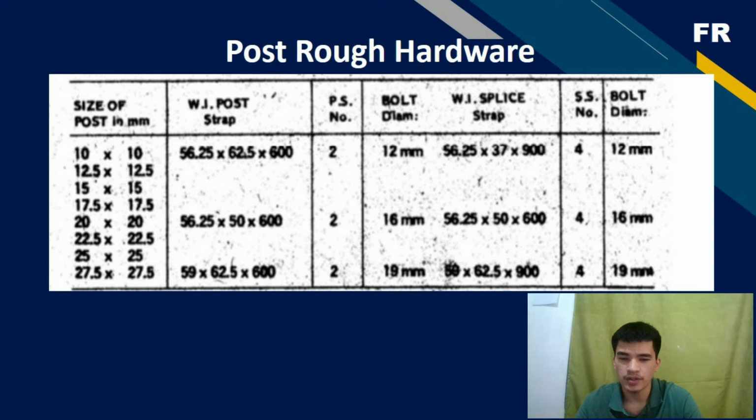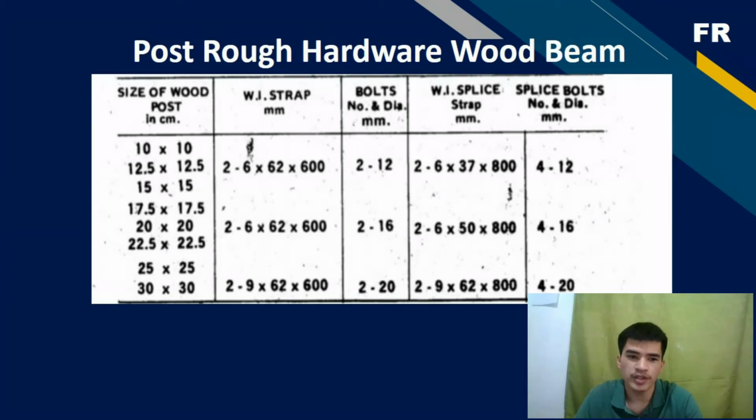So for the US, a quarter 20 by 2 would mean that the diameter of the screw is a quarter of an inch and there would be 20 threads per inch, because the US or imperial method uses threads per inch. The diameter is a quarter of an inch, there would be 20 threads per inch, and the length of the screw would be 2 inches. There would be 40 threads.